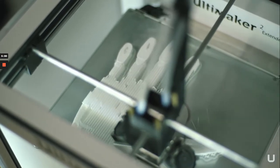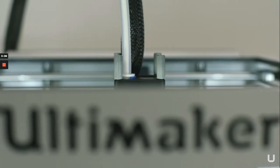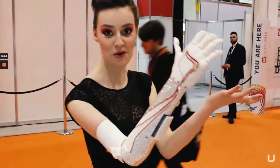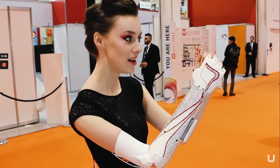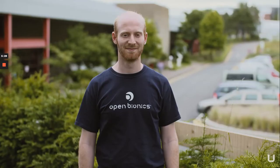rigid. We use the flexible parts for the joints of the fingers, and it means that we don't have loads of different parts to manufacture either. We can print the finger as an entire unit with all of the joints built in, and then it just works straight off the print bed. It's so awesome seeing the reactions from people wearing it for the first time and trying it out. Some people have never worn a Bionic Hand before, and seeing the satisfaction on their face when they get it to move is really, really cool.